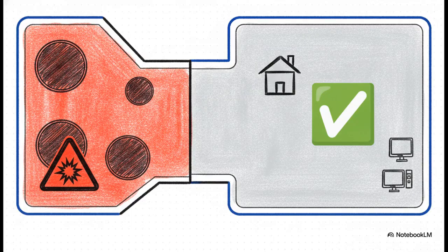To really picture this, notice the stark contrast in these environments. Your Zone 0 red areas are continuous, extreme danger zones. Compare that to the gray areas, the living quarters, or the control room. Those are classified as safe spaces, where standard industrial equipment is perfectly fine to use. Your location on the rig heavily dictates your engineering requirements.